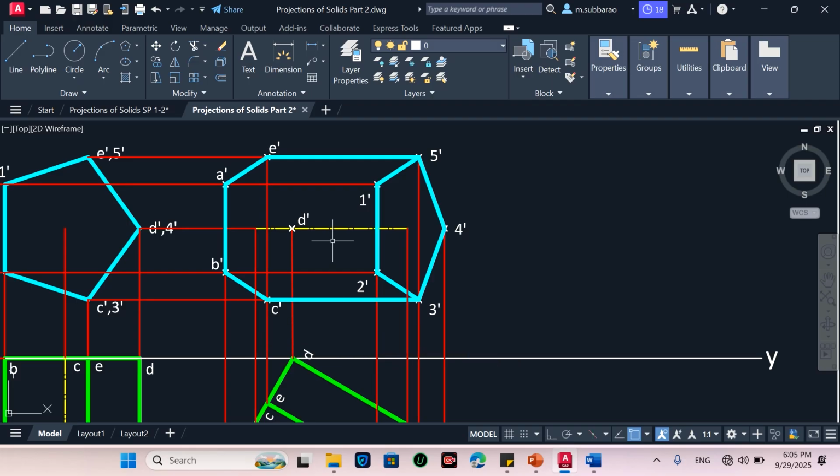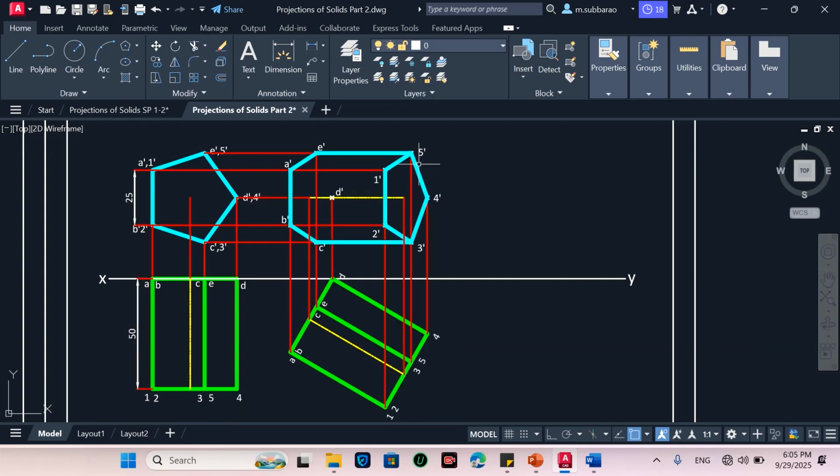Then this is the top base. I am able to see all the outside lines are visible. So now how to identify the hidden lines? I have given one concept: you draw an imaginary line. Let me draw it, I will delete it later. If I draw an imaginary line, whatever edges are on this side are all visible, and whatever is not there will not be visible.